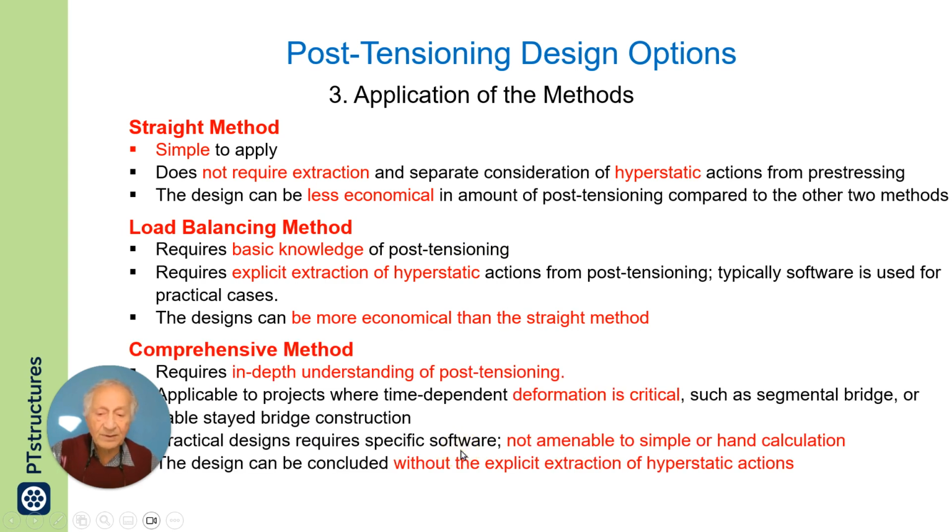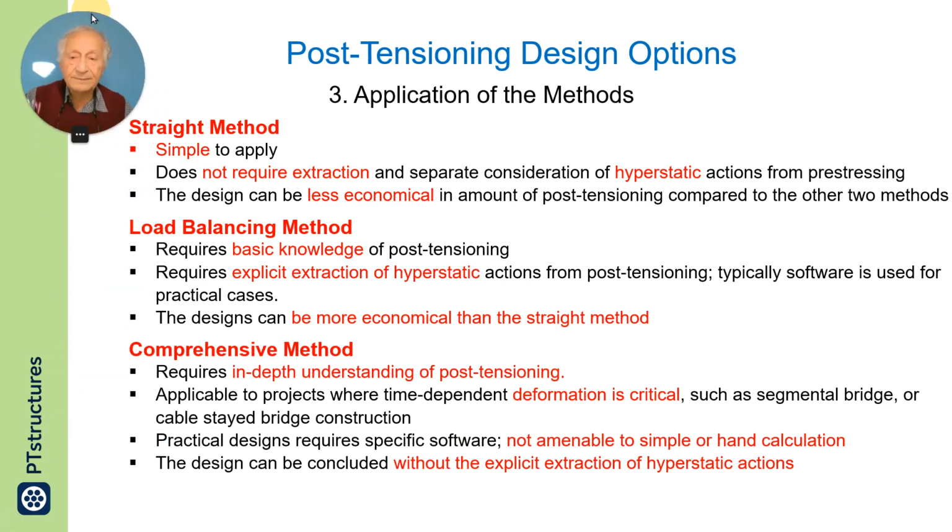The comprehensive method requires in-depth understanding of post-tensioning. It is applicable to projects where time-dependent deformation is critical, such as segmental bridge construction or cable-stayed constructions, or other constructions where deformation plays a great role. Then you have to use this method. Practical design requires specific software, not amenable to simple hand calculation.